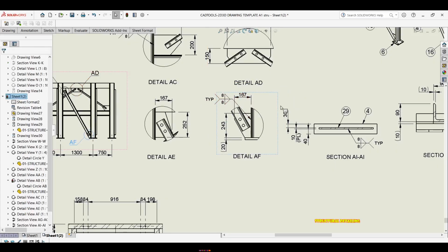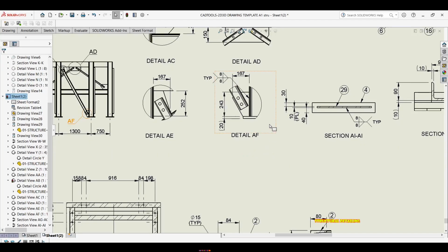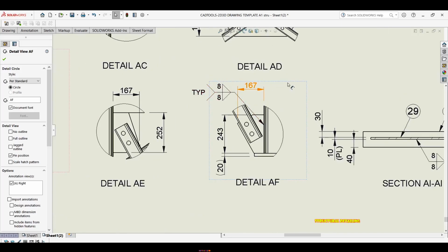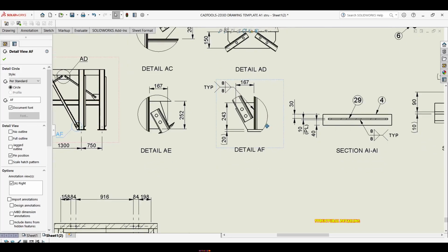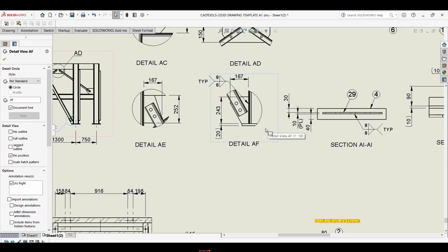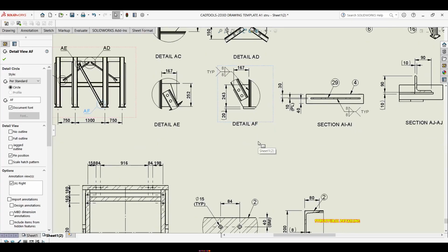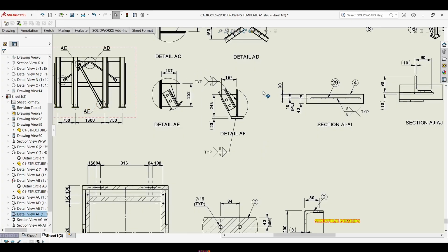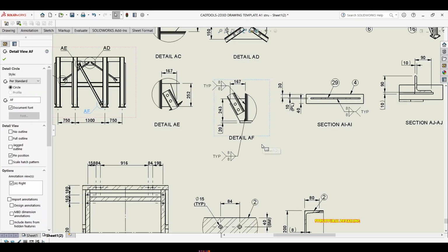But if you copy, you have to click, activate the viewport, let it be blue, make it blue. You see, there's a blue border around. It's activated. Then you Control V, you paste. But if I didn't do that, let's say I didn't, you'll see what will happen. I'm just clicking anywhere, it's not selected, okay? I'm gonna copy and then I'm gonna point it right there. You'll see what happens. Oh no, it does go with it.